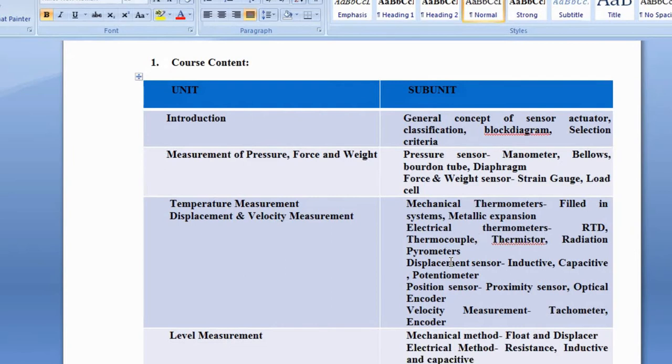But the main thing in this course that I have added here is the potentiometer with loading effect and without loading effect. That is a very important part, meaning how to calculate the errors, the absolute errors and the relative errors. In the ideal condition, the potentiometer will show a linear curve, but in the practical case, it will show a non-linear one. So that error could be determined. You performed that yesterday through the numericals also. So the problem is very important.